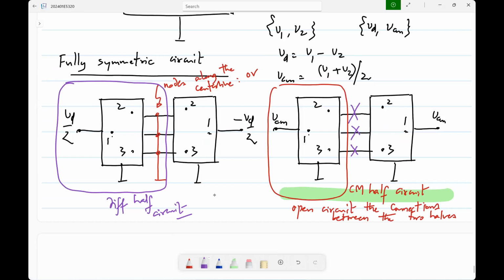So now we'll go about converting the op-amps that we have into fully differential op-amps. Okay. Because finally we'll be making fully differential everything. The amplifiers will be fully differential, etc. Now, we use the op-amp in a feedback loop. If every op-amp has 2 inputs and 2 outputs, again, you can imagine that there are 2 feedback loops. Again, we don't think of it as 2 independent feedback loops for each voltage. We will think of that as a differential feedback loop, which will give you the function that you want, amplifier, filter, whatever it is. And then a common mode feedback loop, which will make sure that the common mode response is 0. Okay, that's the idea.